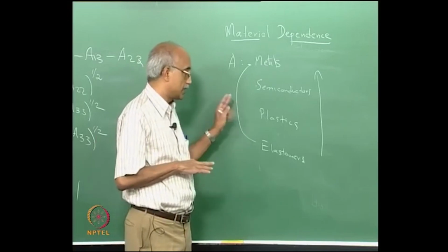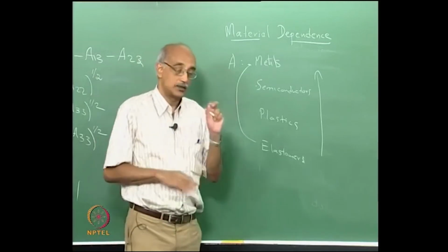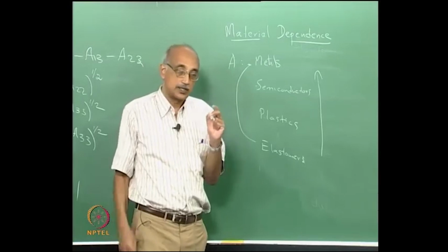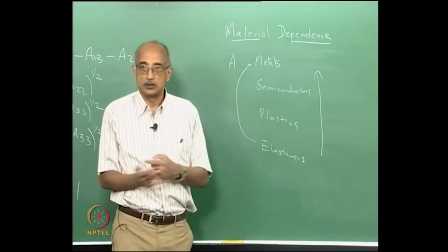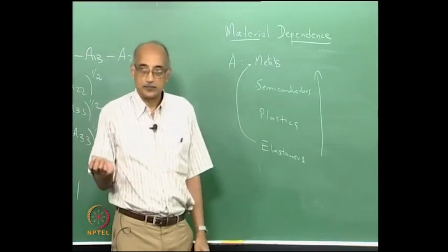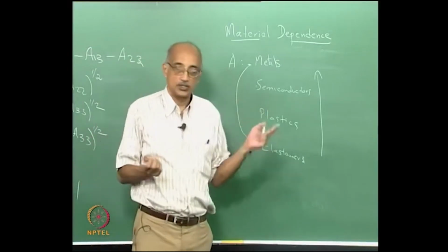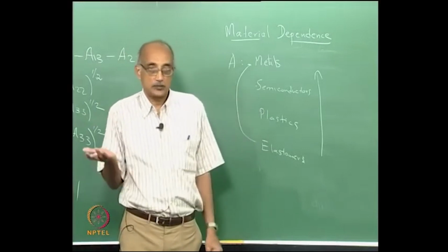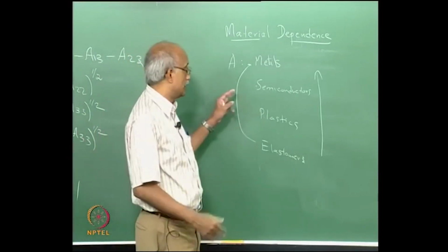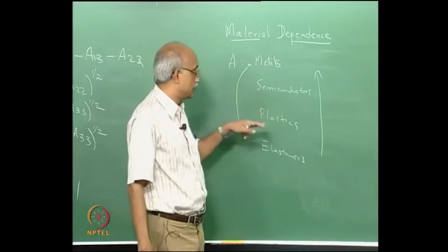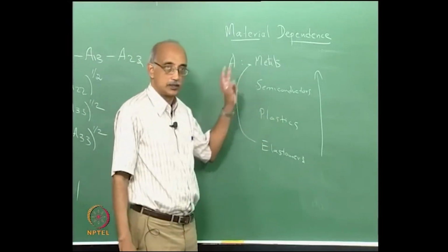And again, remember that we are only talking about one type of adhesion force. The net adhesion force is a combination of all the ones that we talked about. So you may choose a material which minimizes one type of adhesion force, but at the same time it might actually increase another type of adhesion force. For example, if you are trying to reduce Hamaker constants, you might want to use plastics instead of metals, right?